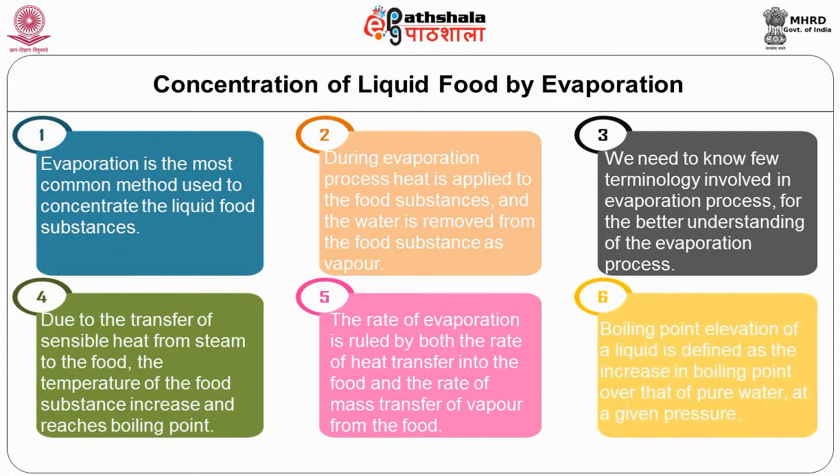As we all know, boiling point of water is the temperature at which the water boils at a given pressure. Boiling point elevation of a liquid is defined as the increase in boiling point over that of pure water at a given pressure. During evaporation, water is removed due to the supply of heat. This increases the concentration of the liquid foods. This in turn increases the boiling point of the remaining liquid.